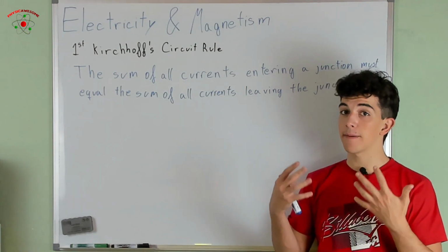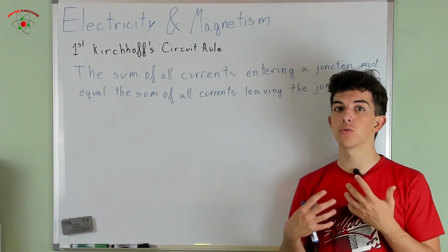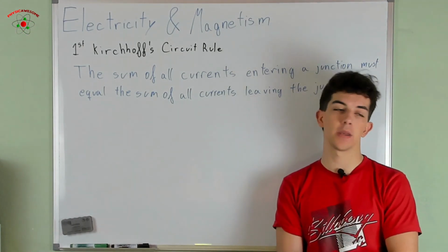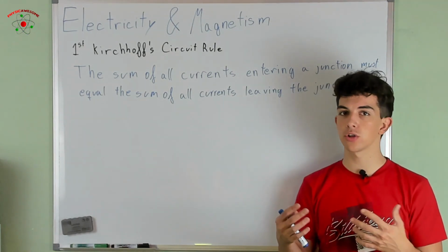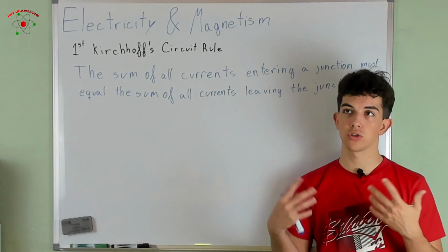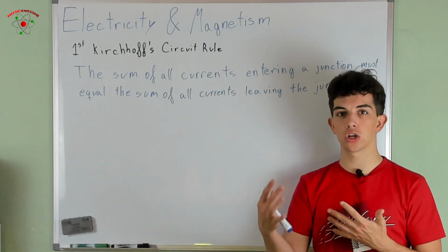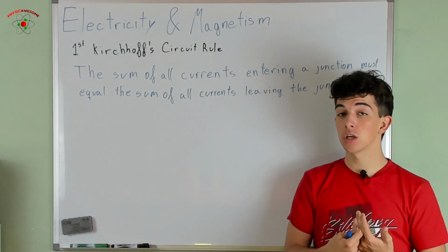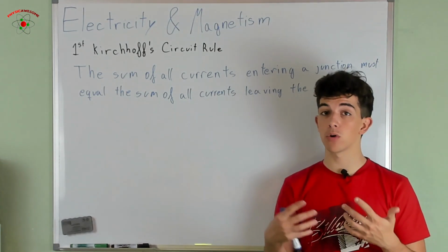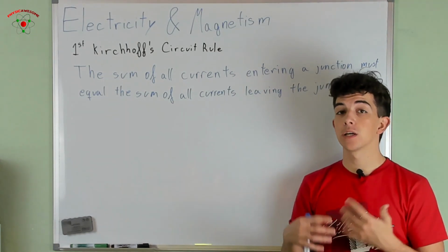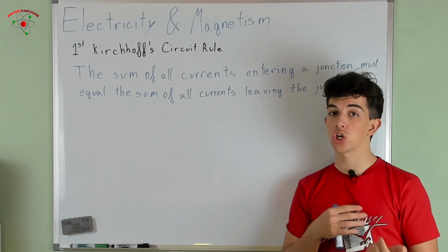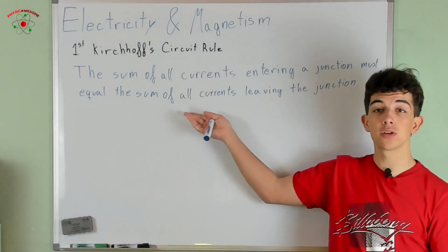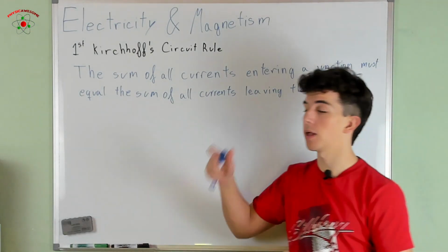So in every junction that needs to happen. On our elements, different things may happen, such as charge accumulation, or a charge not creation, but like taking charges away from some metals, etc. But at junctions, in the way that we portray them in our circuit diagrams, there cannot be any charge creation or destruction. Therefore, the first Kirchhoff circuit rule must apply.